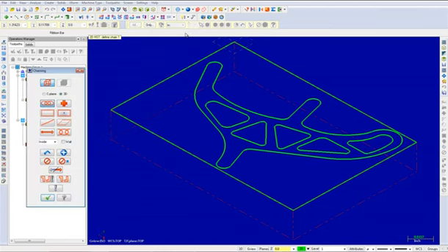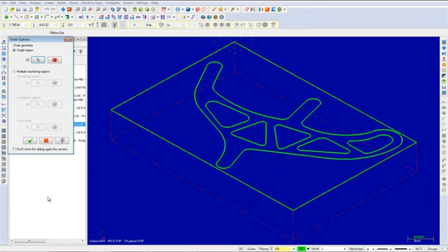When the chaining dialog box appears, leave the default settings. Select the first rectangle as shown. Then choose the outside edge of the part as shown. This chain represents the profile which we want to machine to. Once both chains have been selected, choose the OK button to exit the chaining dialog box. Again, select the OK button to exit the Chain Options dialog box.